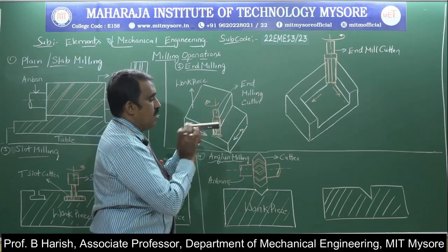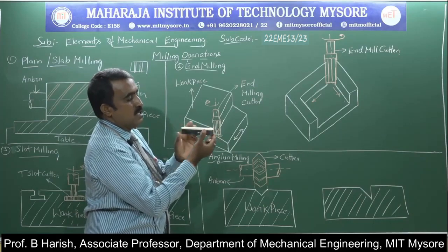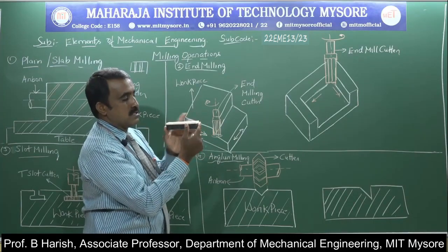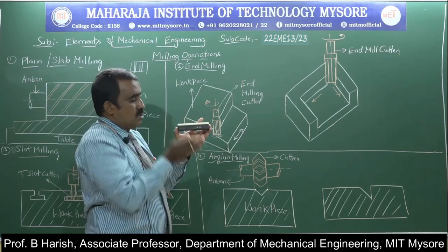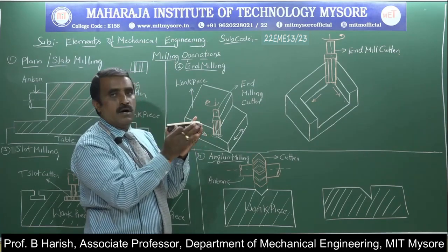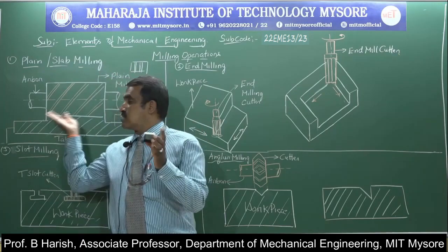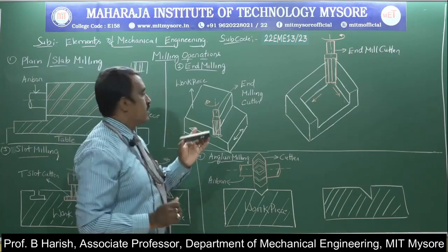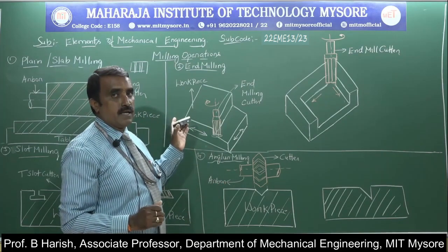That is here, or it can be this end also. Four ends are there. As the cutter is brought in contact, material is removed, so the end surface will be flattened. Here is the flat surface, here the end surface. That is one particular operation performed in end milling.